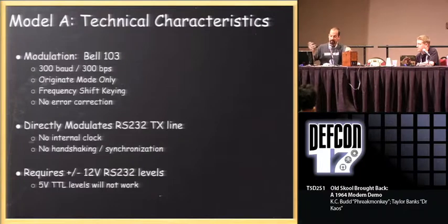It requires the full plus or minus 12 volt RS-232 levels to work, and the reason that's significant is somebody said this some years ago, and I could not find on the net who it was. Somebody said in another presentation that RS-232 is really more of a rumor than a standard. And I wish I could cite the person who said that because it was a brilliant quote. It's true. If you look in the IEEE standard for RS-232, first of all, there's no connectors specified. The pinouts were invented by each vendor who needed them, which is why we went from 25-pin to 9-pin to RJ45, and why sometimes those pinouts aren't always the same. That was never specified as a standard.